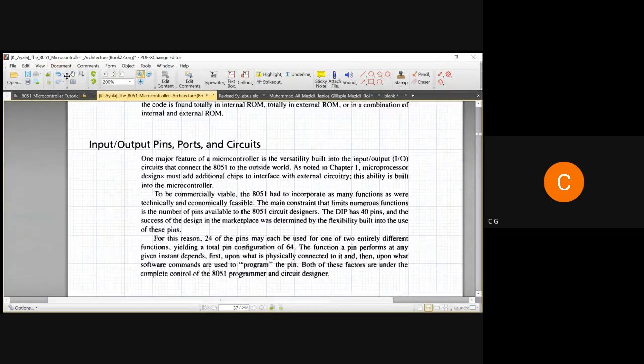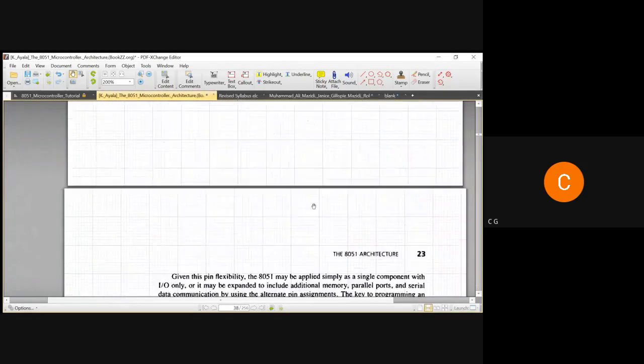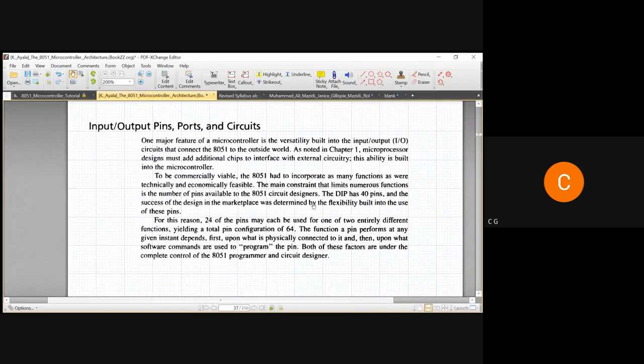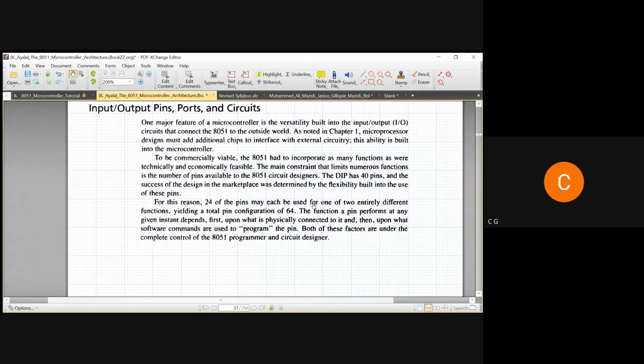Now, in this pinout diagram, there are certain external circuits employed. Either you have a clock pulse generator using a crystal oscillator, or you have an RC network circuit, resistor and capacitor, which can act like an oscillator and give you stable multivibrations, which serve as a clock.